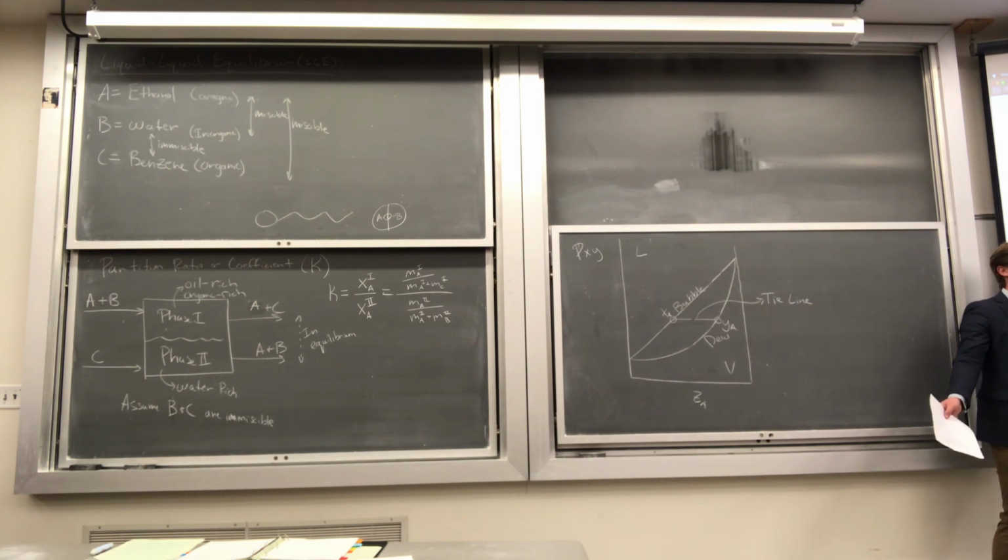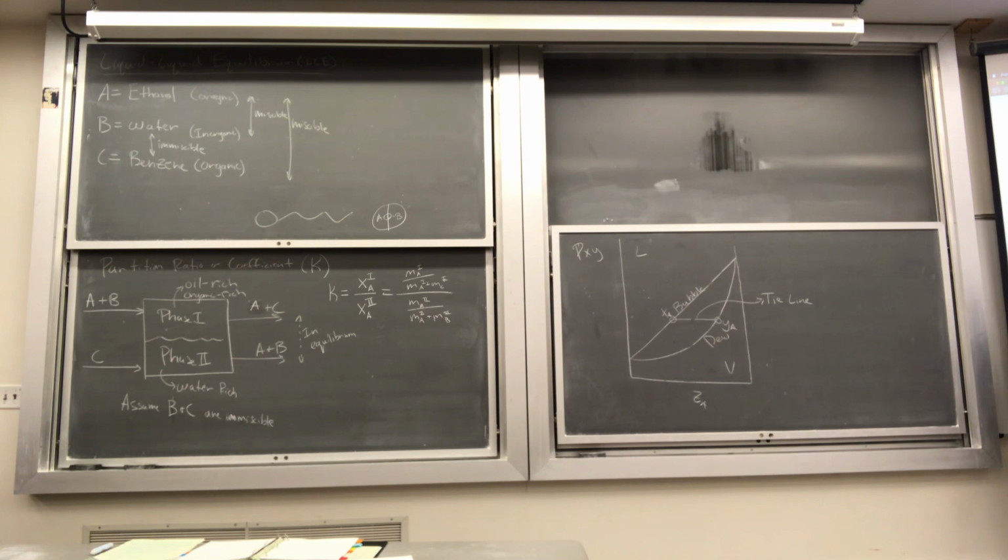The same thing we just did. Right, but there's no tie line. Estimation. Right? So how do we draw the tie line? Do I draw it parallel to this top line? Do I draw it parallel to this bottom line? No. I have to draw a tie line that perfectly matches the same relative position as the point that I'm trying to go to, right?